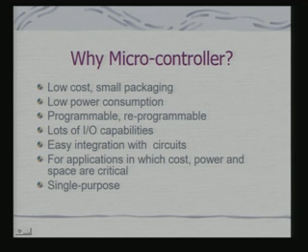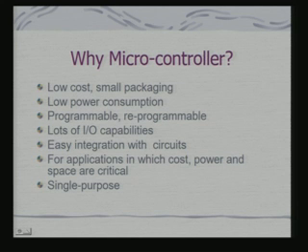We will find that on microcontrollers, on the chip itself, we have a number of I/O capabilities, because I need to interface external devices, which are sensors as well as actuators, and it provides for easy integration with external circuits. And foremost, as I already stated, since I am having single purpose usage, I can manage with less sophistication on the processor hardware itself. That is why I have other peripherals integrated onto it, get a complete system with a small footprint, with smaller power consumption, and that is basically the reason why I go for microcontroller for embedded system design.